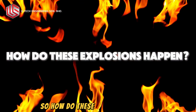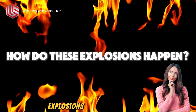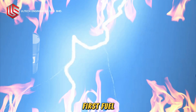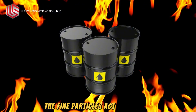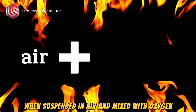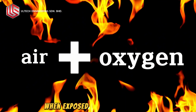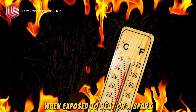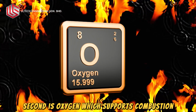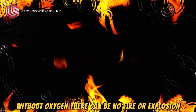So, how do these explosions happen? The key to understanding combustible gas and dust explosions lies in 5 factors. First, fuel. The fine particles act as the fuel. When suspended in air and mixed with oxygen, they form a flammable mixture that can ignite when exposed to heat or a spark. Second is oxygen, which supports combustion. Without oxygen, there can be no fire or explosion.